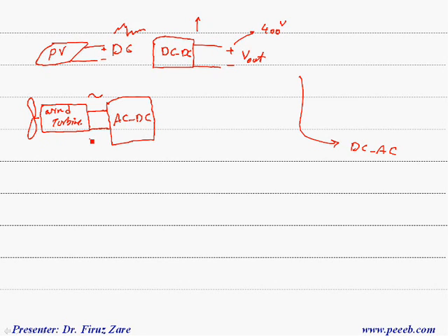That means if the frequency and voltage fluctuate, here we get DC voltage, and the voltage across this output is not regulated. So another possibility is we can use, for example, a DC to DC converter again. That means we can regulate this voltage, and here we can get the same voltage as this voltage level. That means we can design this converter in such a case to get 400 volts.